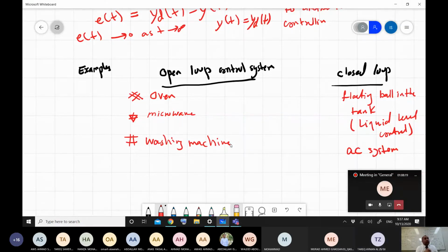Yes. So if you are an engineer and I need a solution, the first thing you will try, the open loop or the closed loop? Open. According to the problem, there are things where open loop is better. So simply, if you need to sell anything, you need to reduce the cost. This means that you'll ask yourself in the first stage, can I solve this problem using open loop? In one condition, the process by itself must be stable.